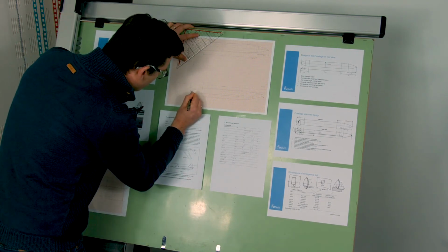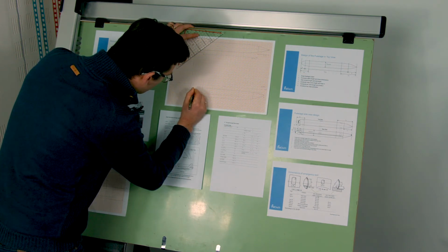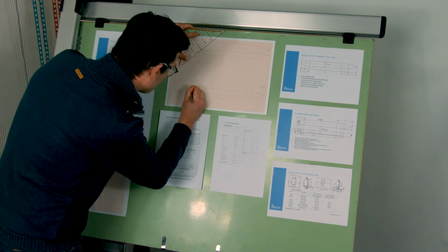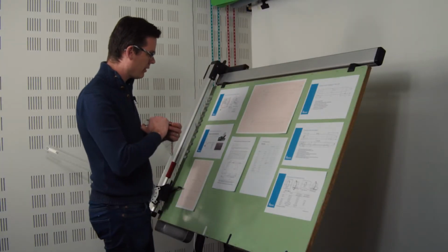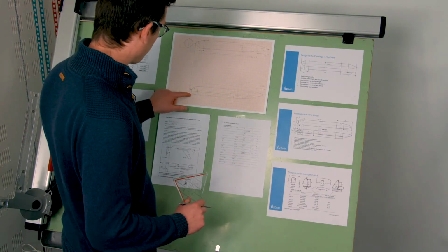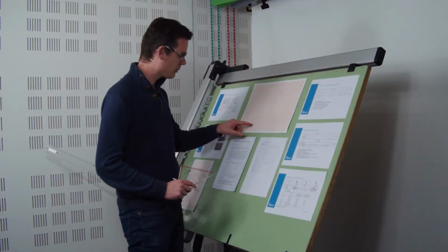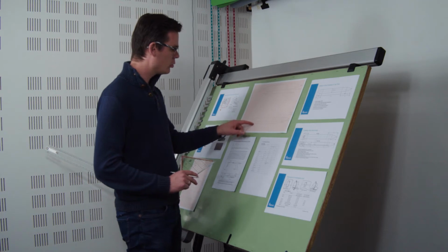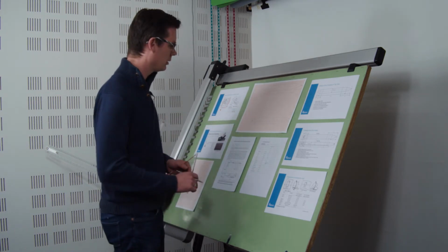And then for the nose, I need to make sure that I draw the nose under this windshield, right? But then not longer than this box. So I have a nose shape, I have a windshield. So we have here space for the weather radar, and below the floor we have some volume available where we can store the nose wheel of the nose landing gear, if that turns out to be the right location.